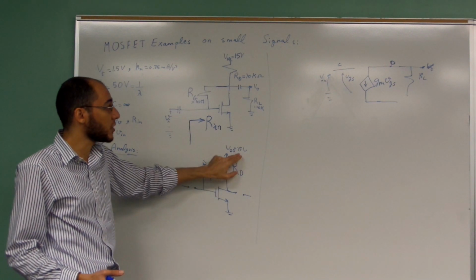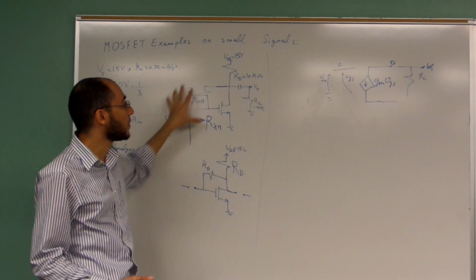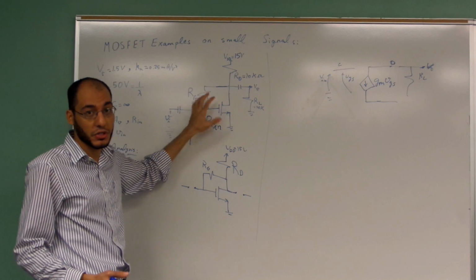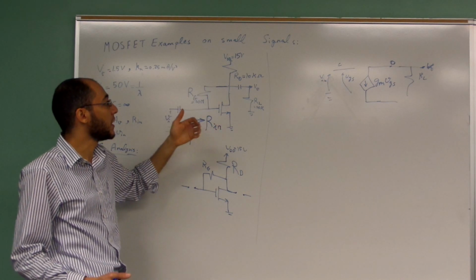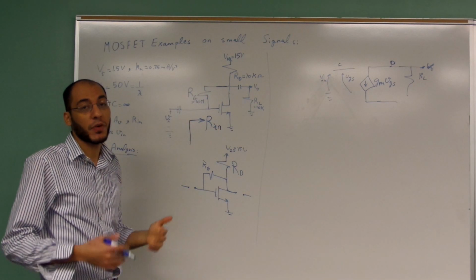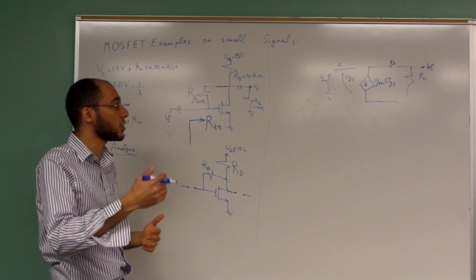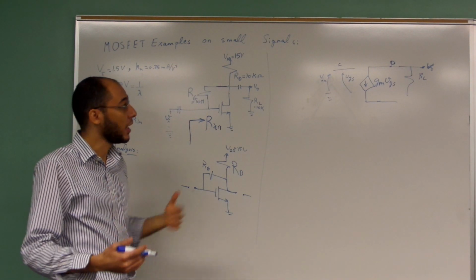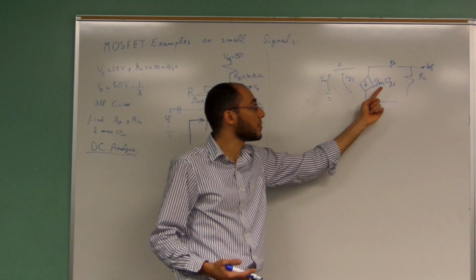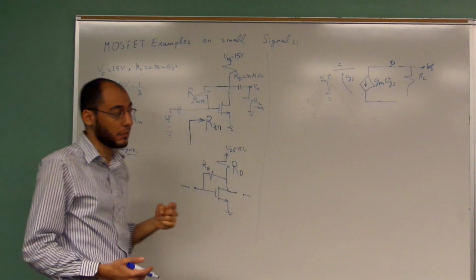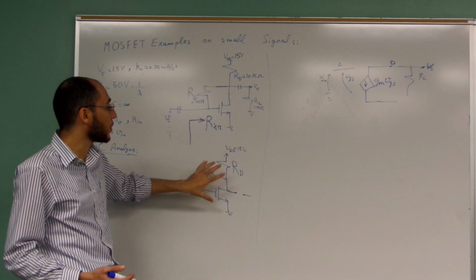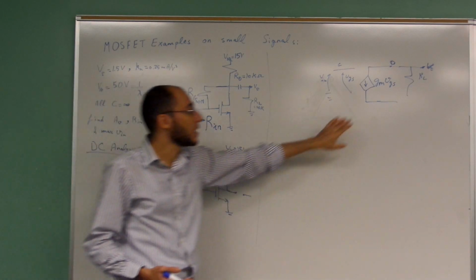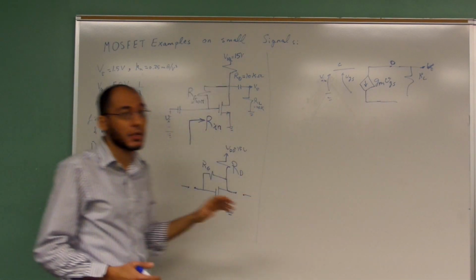If you change this voltage, then you expect a different response from the circuit. You might not see the amplifier amplifying that much, or perhaps if you increase the voltage, you might see it amplifying a lot. How is that? That comes into the picture through the value of GM. So the configuration of the DC affects the value of GM, and thus affects the whole gain.